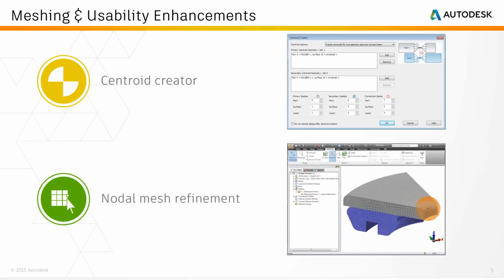Typically, what you want to do when you're connecting multiple parts together like this, with this connections technique, is you want to say that the primary spokes that Marwan's highlighting right now are rigid elements, and the secondary spokes are also rigid elements, but the connection spoke is a beam element. And the only way to do that in Simulation Mechanical is to consider them as different parts.